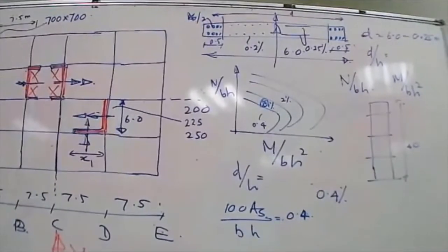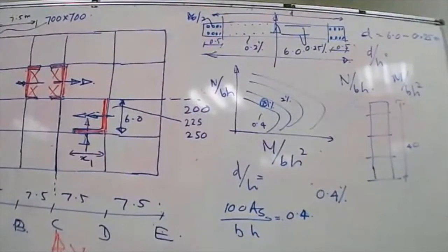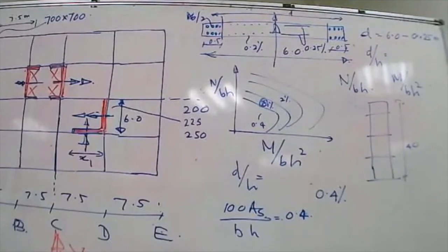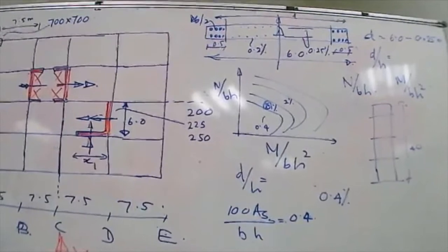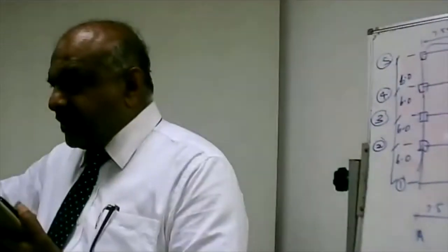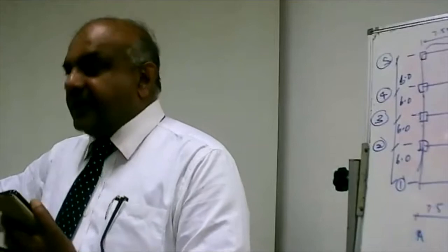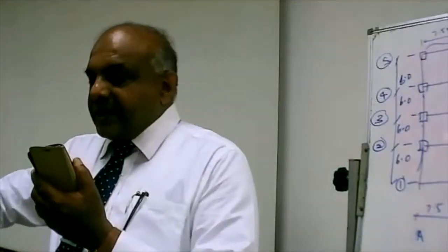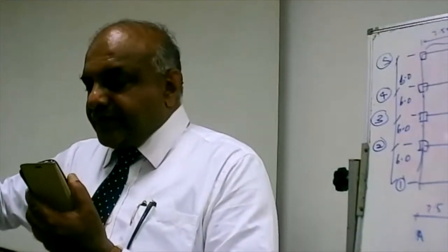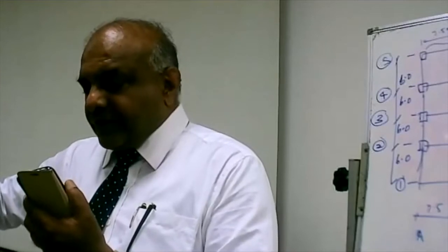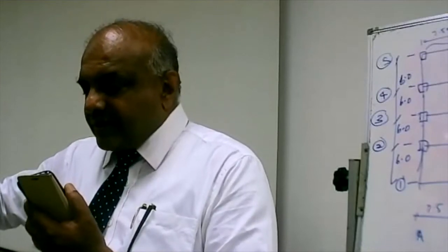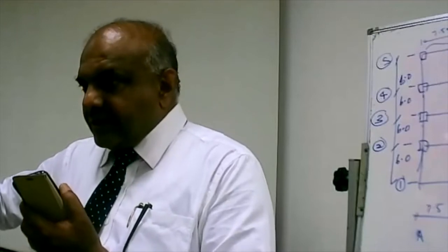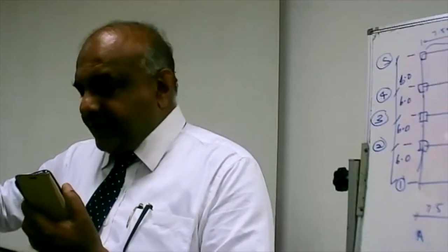So there is one question in the chat box. Yeah, what is the question? Do we need to consider notional load or imperfection load with the wind load? Yes, always you have to consider a notional load. A notional load is given in the Eurocode as well. In the British code, it is 0.15% of the dead load, that we call 0.0015.